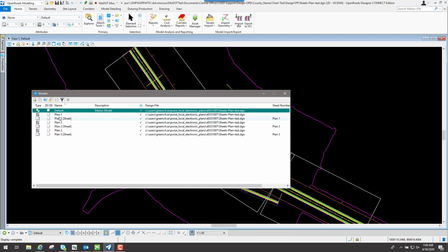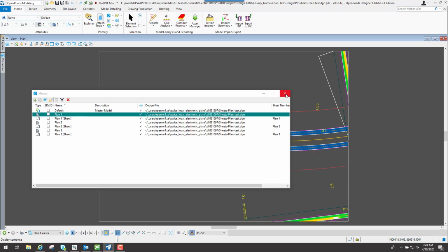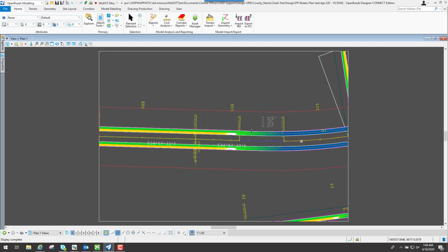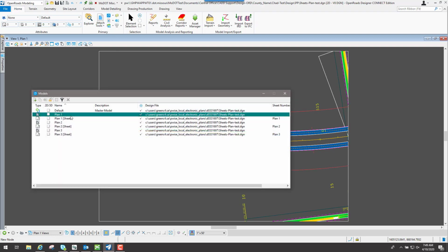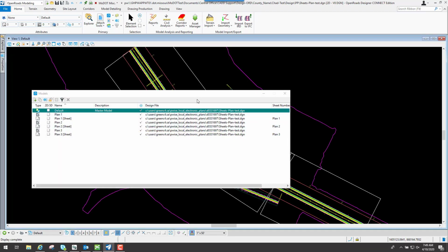Now I also mentioned that it creates a drawing model. So if I go to the drawing model, that's what this looks like right here. Basically the clipping shape masks out everything outside of it. And if you want to add some other stuff inside of here, like certain notes or text or whatever else that really doesn't need to be on this default sheet, that's where you would add that particular information.